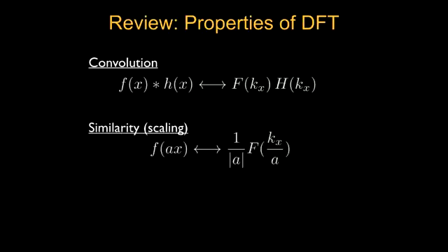Another thing, when you multiply by a constant here, when you apply the Fourier transform, you have to divide it. I think we covered this last time too: when you have a rect times some constant value, in the sinc domain you have to divide by something. So once you stretch it, in the Fourier domain you have to squeeze it.